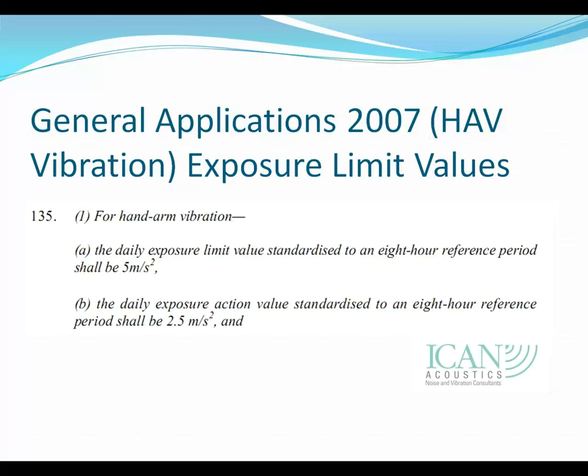It relates to the on time of that equipment. Sometimes for pneumatic tools, we use a trigger on time measurement device. Whenever the pneumatic tool is used, it commences the clock, so you can work out exactly what the on time for that machine was for a given operator over an 8-hour reference period.